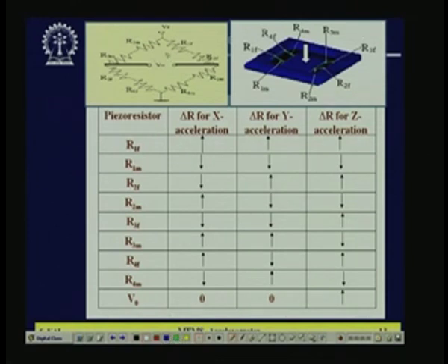So now R1M and R3M are connected. M stands for mass end and F stands for flexure end. So you can see the opposite arms. So 1 and 3, the M are connected. In opposite to that, 2 and 4, the M are connected, mass end resistances. Similarly, the other two sides of the Wheatstone's bridge, the 1 and 3 here, 2 and 4. So 1 and 3 is here, 2 and 4 here. So 1 is the flexure end, mass end, like that.